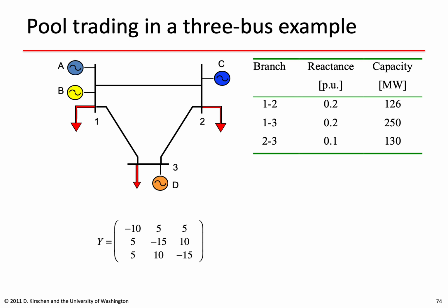These equations involve terms coming from the admittance matrix of this network. So we need to build this admittance matrix, and to do that we go back to the table that was giving us the reactance of the branches of this network. The off-diagonal terms of the matrix Y, the admittance matrix of this network, are given by the admittances of the branches.